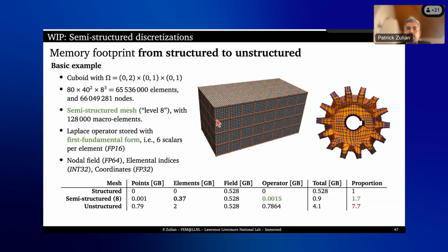It's just that the storage of the mesh is more efficient, meaning that it's not a domain decomposition approach. This is purely continuous Galerkin. It's a standard finite element discretization. It's just the way you store it that makes the difference in terms of performance and also in terms of memory footprint. So same exact outcome, just different storage. Makes everything viable on a laptop. I think the largest problem I solved on a laptop for this Laplace problem was a single precision 1 billion degrees of freedom. So you can really push it. If you push it, you can really use small resources for a large number of degrees of freedom.